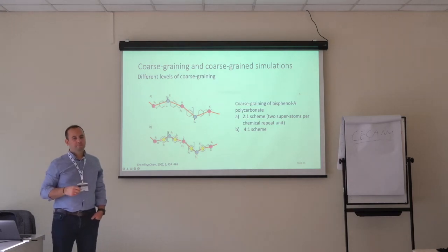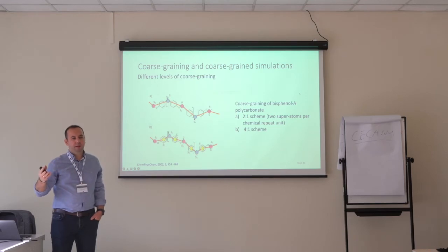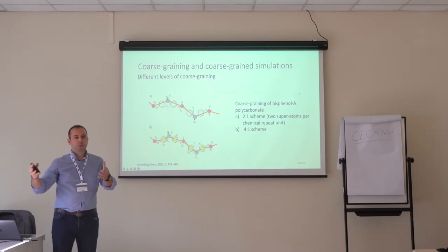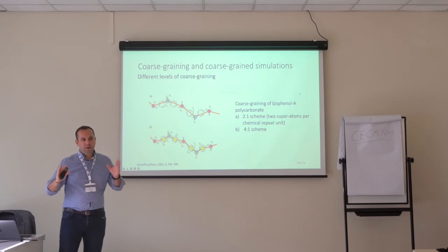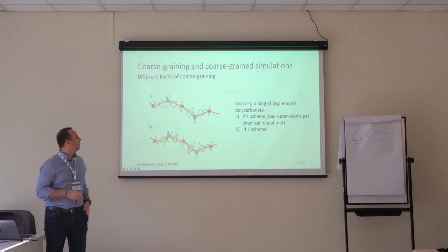So from the chemistry point of view, can we say that we group two atoms with similar electronegativities? Yeah, I mean, it is more based on functional group. For example, if you are considering an epoxy, you don't really cut the reacting part into two. Or if you are, for example, modeling a polyurethane, you don't want to cut the cross-linking junctions into two. You want to combine them together such that you have a proper modeling of the reactions. So that's why you need some sort of chemistry knowledge if you are using a DPD type of approach.